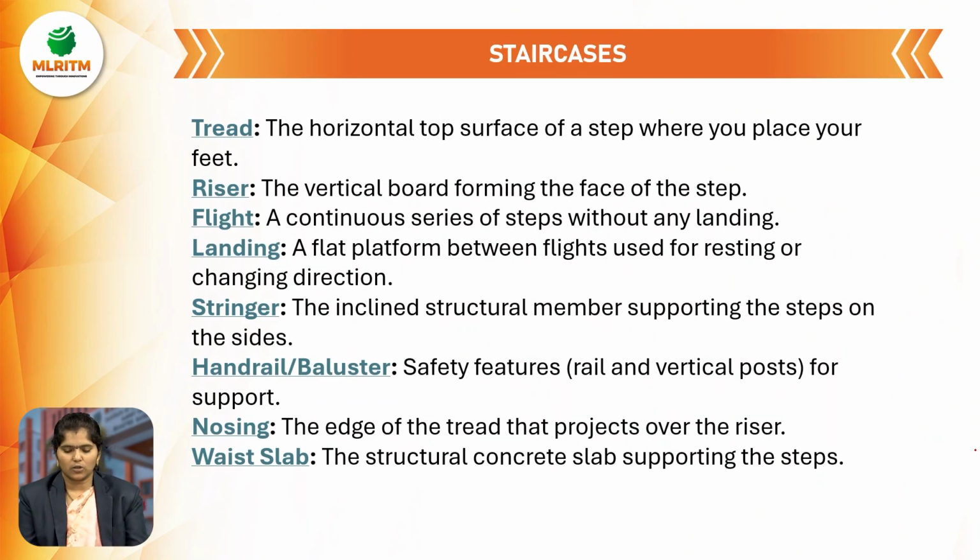The horizontal top surface of the step where you place your feet is called tread. Riser, the vertical board forming the face of the step. Flight, the continuous series of steps without any landing. Landing, a flat platform between flights used for resting and changing direction. So this is called landing.